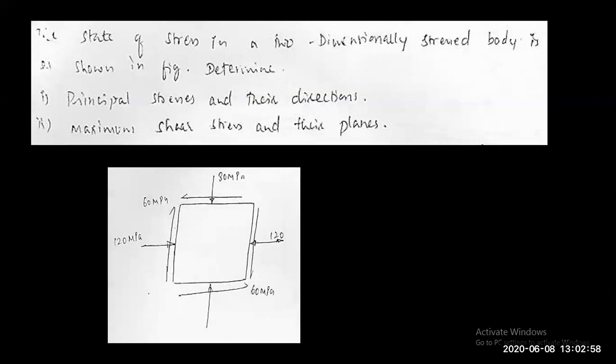these stresses, right? So this problem is a typical one where you have negative values. So if you see the convention here, whenever these shear stress components are arrowed in this fashion, that means towards the top right corner and bottom left corner. So in these two cases, you assume it to be a positive case. Whereas if it is in the other two corners, then you assume it to be a negative case.